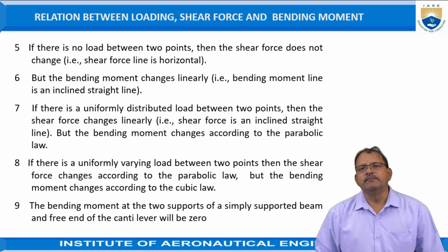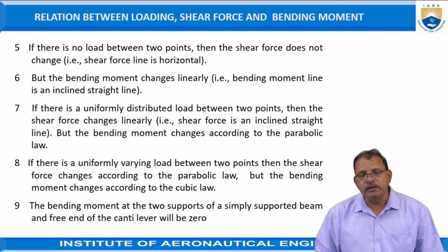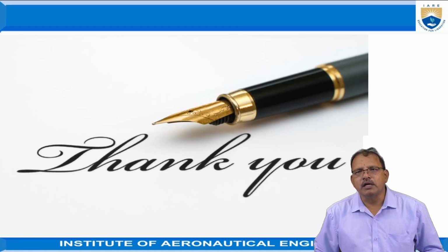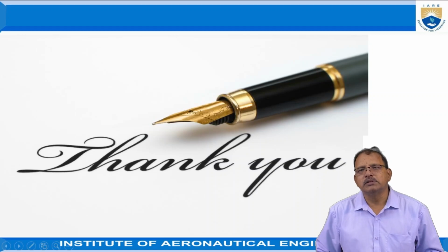Here, the bending moment at the supports of a simply supported beam is 0, and the bending moment at the free end of a cantilever is also 0. Okay, this is the information regarding the types of beams, the different types of loads that act, the importance of the shear force and bending moment diagrams, and the factors that affect the deflection of the beam. This we will learn.